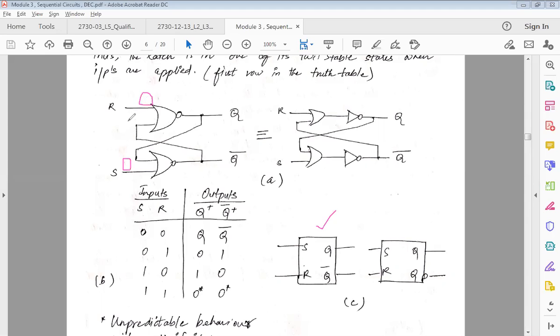So unless I have one of the inputs, let us assume that the value here was 1. So 0 plus 1 is going to be 1, and that is going to be inverted. What is my output here? 0 NOR 1. What is my output? 0. So 0 is going to come and sit here.